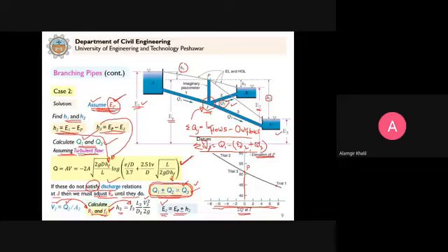And at this point P, the elevation of P value, you can see here that for this P, summation of Q is 0. So this is the required condition, because for this P value, summation of Q is 0. It means inflows minus outflows is equal to 0. And this is the required condition. What is the required condition? That sum of inflows minus sum of outflows should be equal to 0. Clear? So it will only happen for this P elevation here.